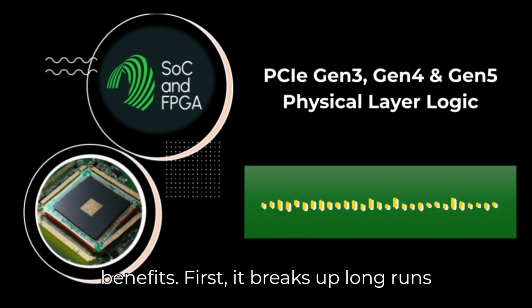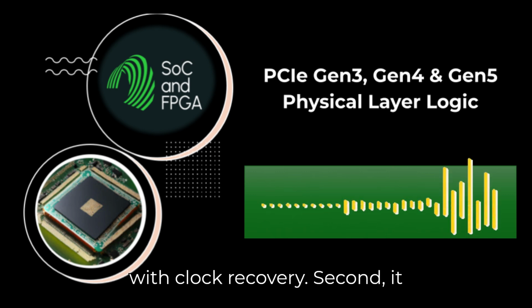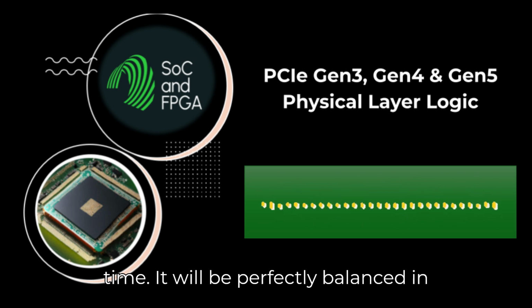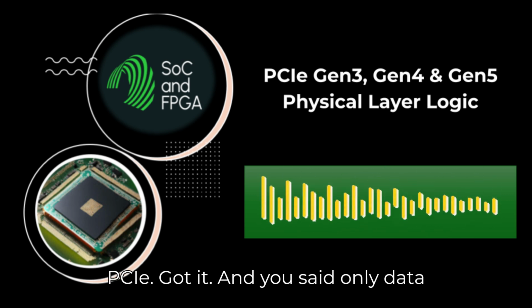First, it breaks up long runs of identical bits, long strings of ones or zeros, which, as we said, can mess with clock recovery. Second, it statistically ensures DC balance over time. It won't be perfectly balanced in every single block, but averaged out, it works for the AC-coupled links used in PCIe. Got it. And you said only data blocks get scrambled.